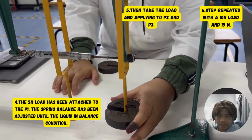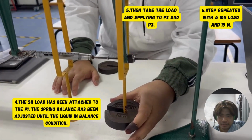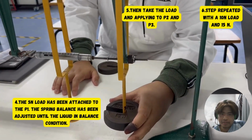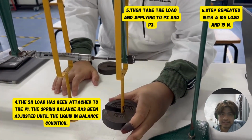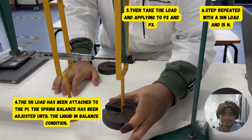Fourth, the 5 Newton load has been attached to the P1. The spring balance has been adjusted until the liquid is in balance condition. Fifth, then take the load and apply it to the P2 and P3. Sixth, the final step is repeated with a 10 Newton load and 15 Newton load.